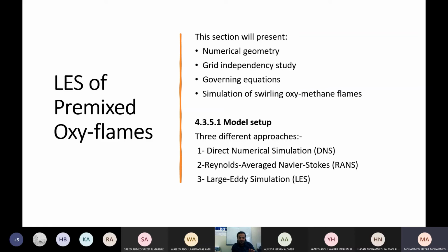Shabab, here when we run the gas turbine and we find the stability map, the line representing the blowout and the line representing the flashback, we find all of these lines, the flame blowout and the flashback, at fixed adiabatic flame temperature. So the flashback line is at fixed adiabatic flame temperature, whatever the value of oxygen fraction, whatever the value of equivalence ratio. And also the flame blowout is at a minimum adiabatic flame temperature for all points. The whole points in the line of the blowout are at the same adiabatic flame temperature. And so we have concluded, Shabab, out of this experiment that the flame operability in a gas turbine depends mainly on the adiabatic flame temperature.